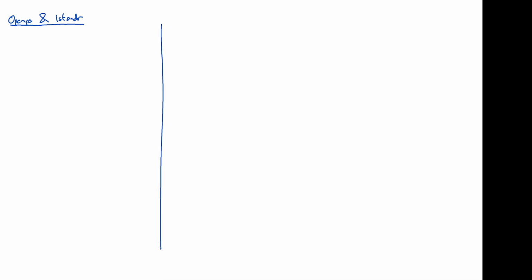Let's talk about op amps. Let's do a quick review. We've got this op amp, and we know that all op amps should have some sort of negative feedback. I'm going to draw it as a question mark, just something connecting the output to the inverting input. What are the two rules associated with op amp analysis? There's two of them. The nodes' voltages are equal: V plus equals V minus if there's negative feedback.